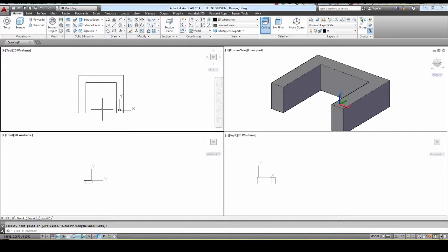then it worked. And the reason it worked in this case here is because we're drawing on this world coordinate system plane, which is this plane up top here. But there may be an instance where your object snaps might get confused, and instead of picking this endpoint at the top, it might actually pick this endpoint down here at the bottom. Okay, there's basically two things going on. We have our object snaps, and we also have this thing called allow disallow dynamic UCS.